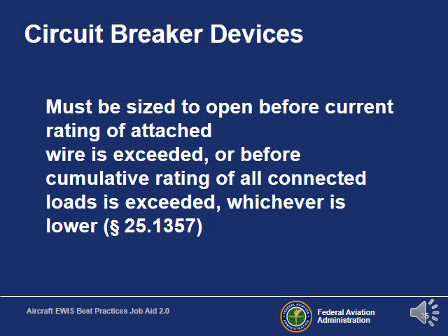Let's highlight a little bit more about circuit breakers. Circuit breakers need to be the appropriate size. If they're too big, they will not cause enough protection for the wire. When there's high current, the circuit breaker will not pop when it's supposed to.